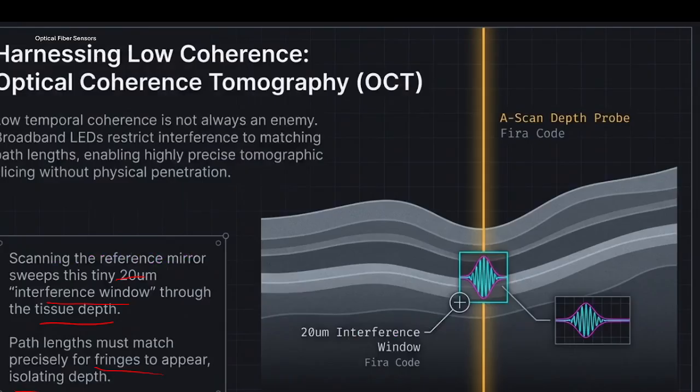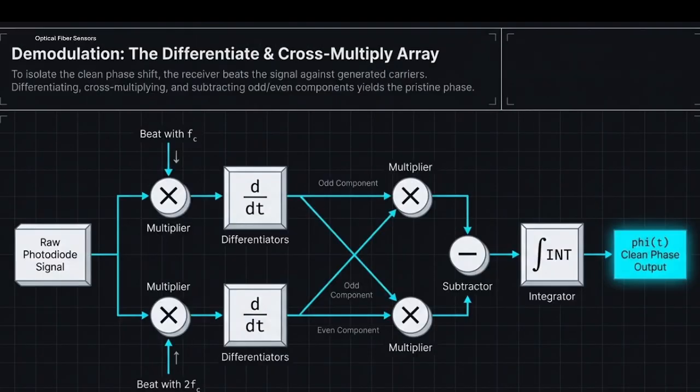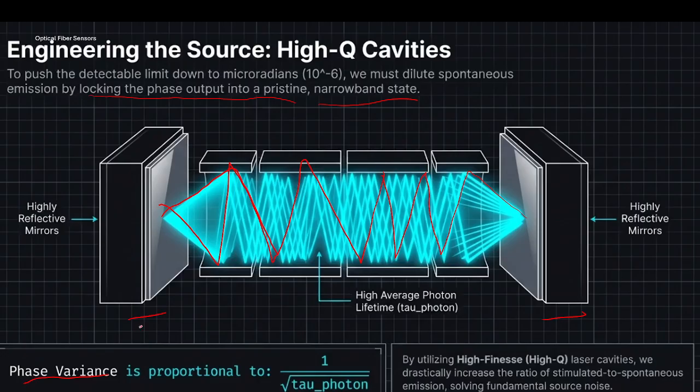Okay, that's what I was discussing here. The lasing cavity looks like an etalon cavity, Fabry-Perot. But if you want a high Q cavity, then you need to go for the distributed, layer by layer cavity, like this.